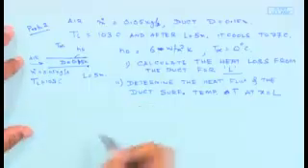If we know the temperature at which the air is leaving, and I know the mass flow rate of the air flowing through this duct, and I know its Cp, I can simply find out the total heat which is lost from the hot air to the outside. So, let us calculate that first.